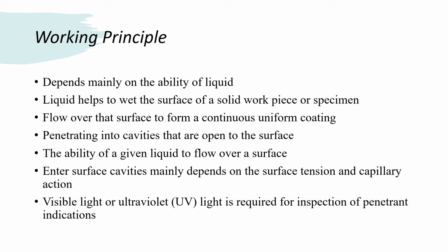Now comes the working principle. Penetrant inspection depends mainly on the ability of a liquid to wet the surface of a solid workpiece or specimen and flow over the surface to form a continuous and reasonably uniform coating, thus penetrating into cavities that are open to the surface.